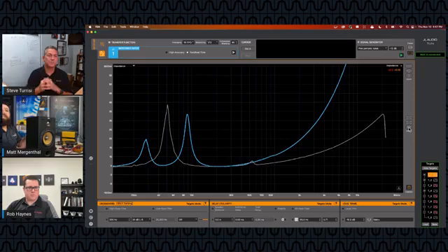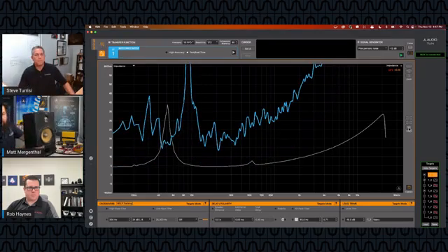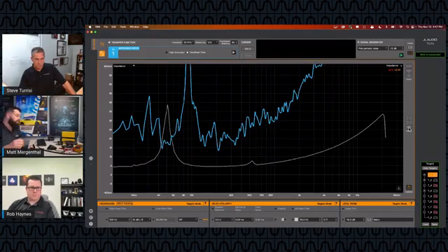So I got one last thing to talk about. Get rid of this enclosure. And what I want to show is some other types of impedance measurements. What we did so far today is a 2-wire impedance measurement where we take 2 wires, we've calibrated it using a resistor, and we connected it to our speakers, and we got a pretty good measurement. But there is one other way that you can get a more accurate measurement. Well, actually, there's 3 other ways, but it's considered a 4-wire impedance measurement.